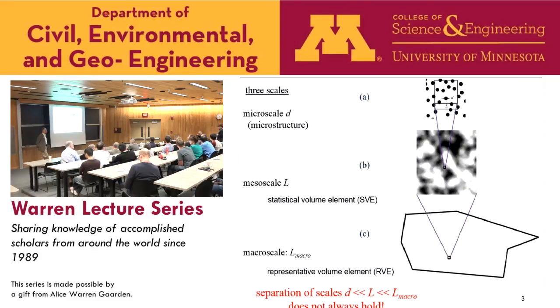My question is probably a little detailed, but in addition to computing effective properties, theoretically, you can experiment as well for the problems which are heterogeneous. For the large deformation problems that you showed, you are using the first Piola-Kirchhoff stress tensor, and you say your stresses are uniform. But they are uniform in the reference configuration, that is, not the distorted configuration.